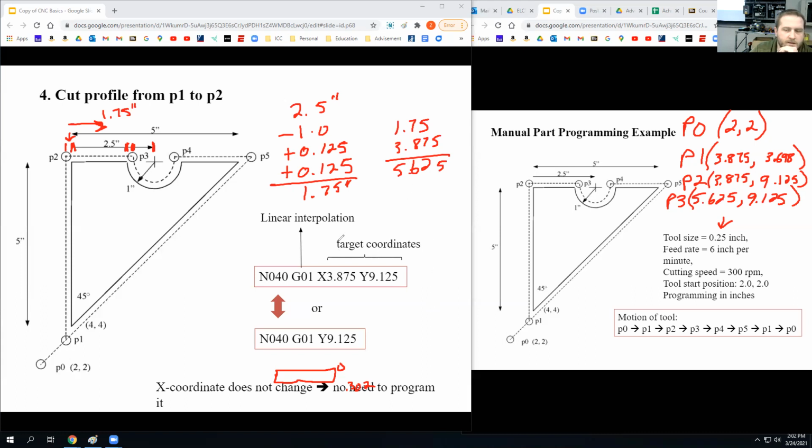Okay. Now we need to improve that number. You want to do another one? The next one's pretty easy. All we're doing is moving 2 inches minus the drill bit. So the next one would be adding to the x direction 2 minus 0.25, so it'd be 1.75, right?